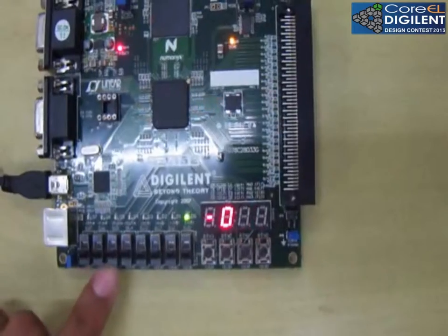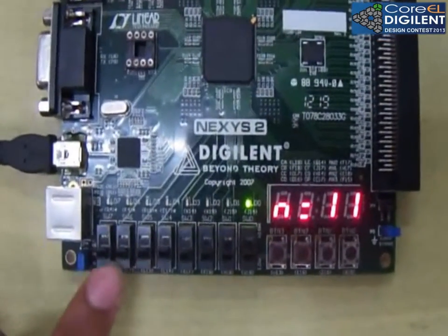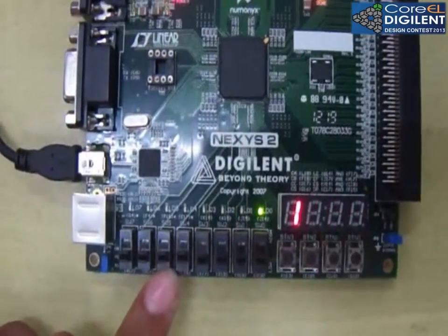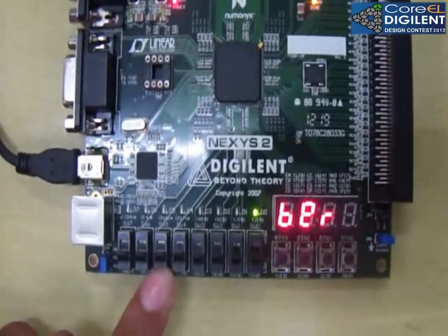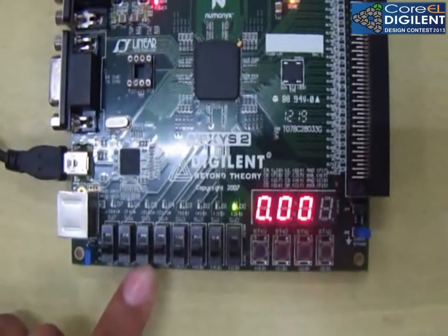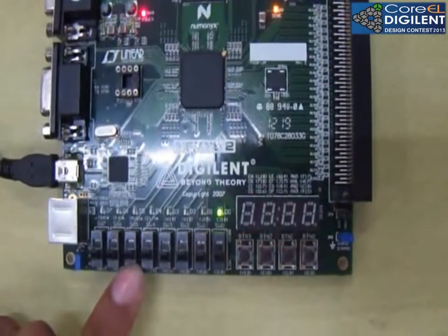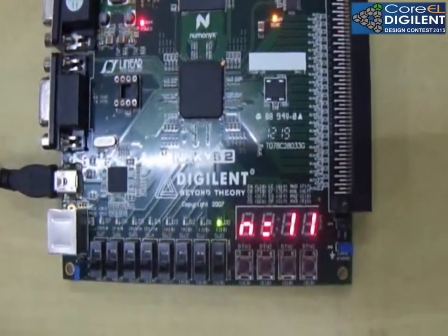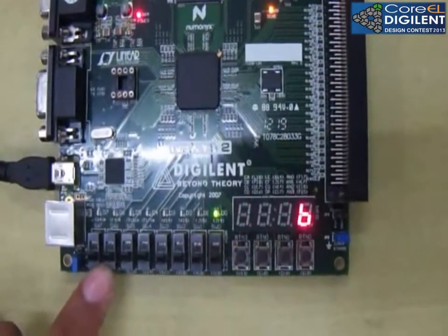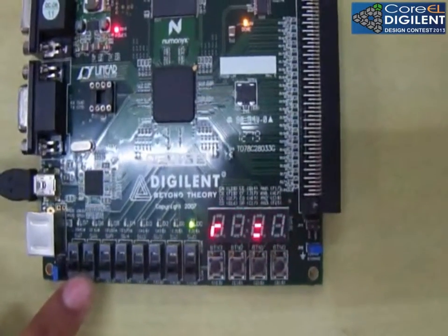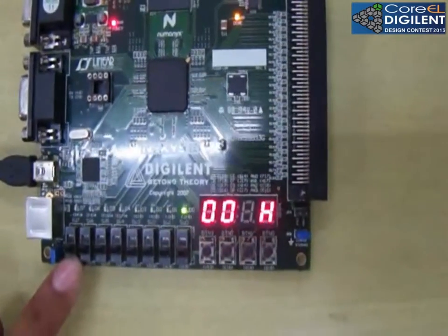So these 3 pins are used for storing these 4 different error rates. This pin is used for switching between the current error rate and the previously stored error rate. So when we want to see the previous error rate, we will make it high. Otherwise, to see the current error rate, we will keep it low. These 2 pins are used to select the particular error rate from the 4 previously stored error rates.